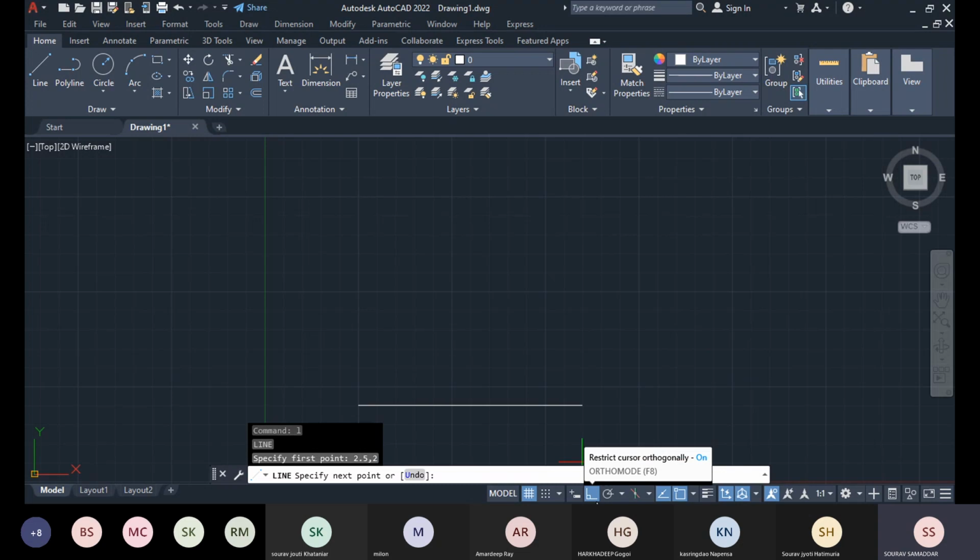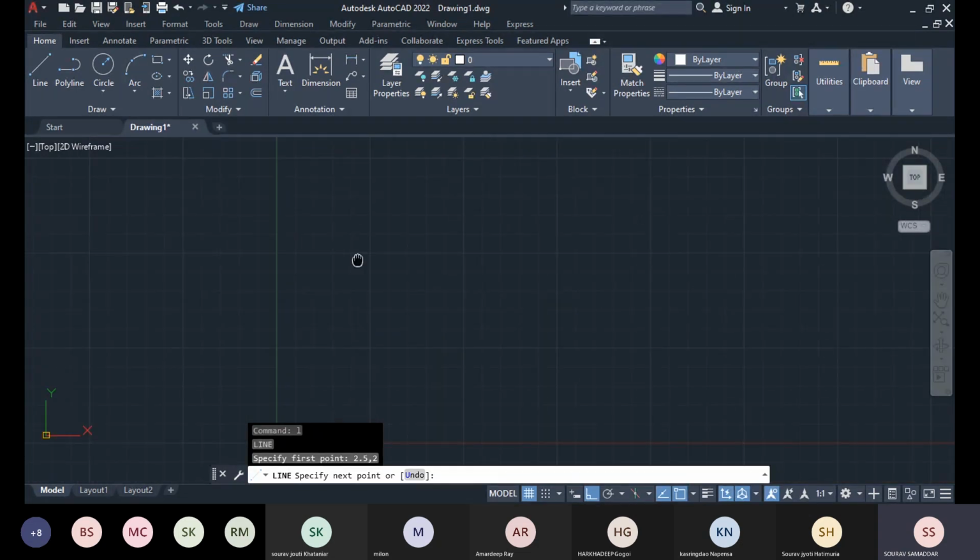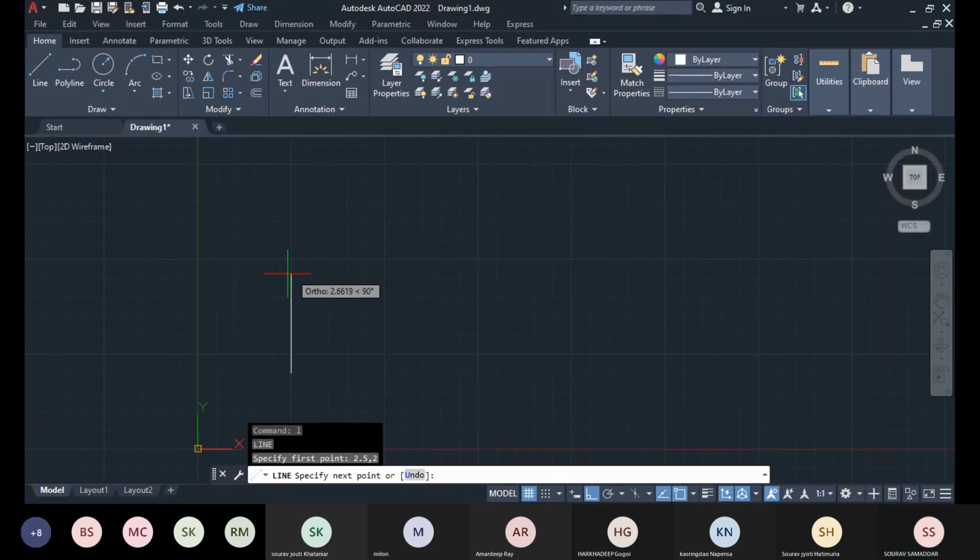Okay, two lines at a perpendicular actually denote the ortho option. Okay, so this one is the ortho option. You have to turn it on, and now after turning it on, just notice the direction. It only moves in a direction that is associated with 90 degrees. See, this is 0, this is 90, this is 180, this is 270, this is 0, 90, 180, 270.